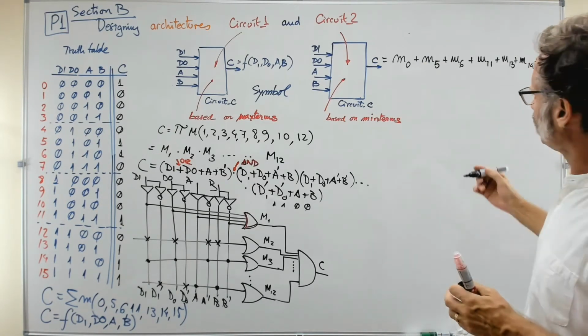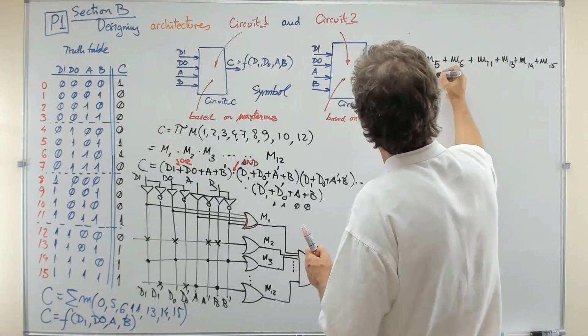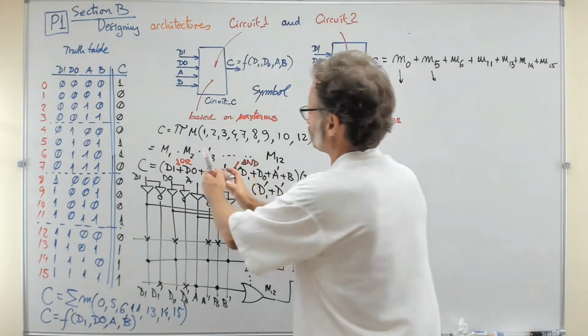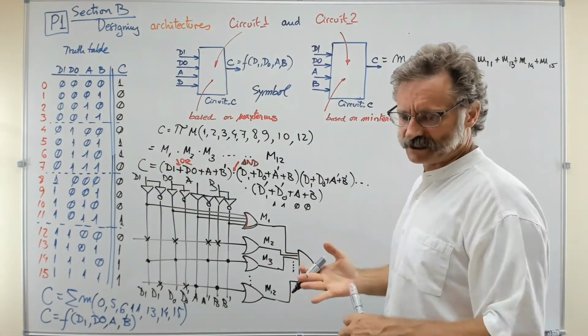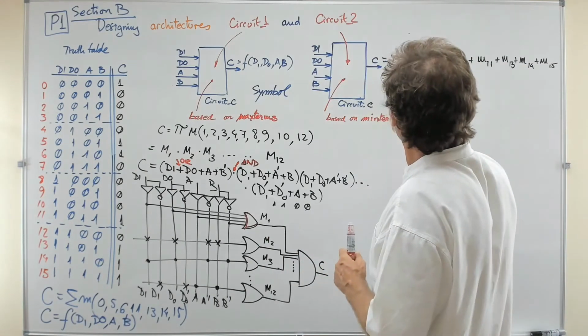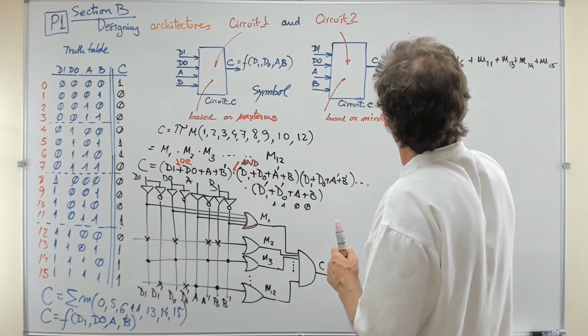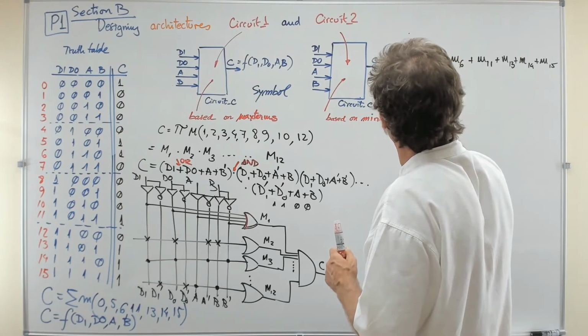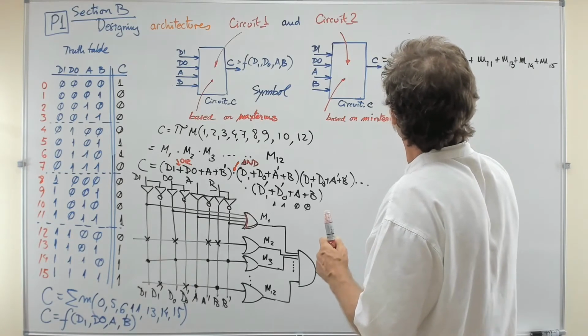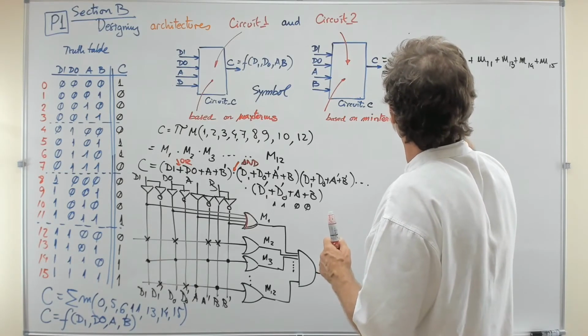So very well, now you can represent every single term in this expanded way, but now as a minterm. And in order to do that, you have to consider again the AND of every single input ordered correctly.